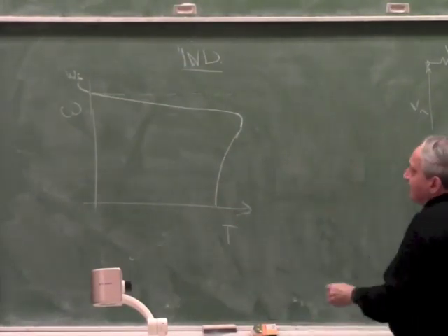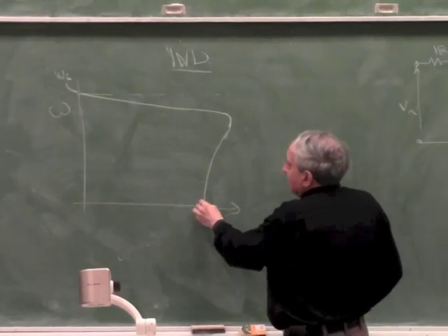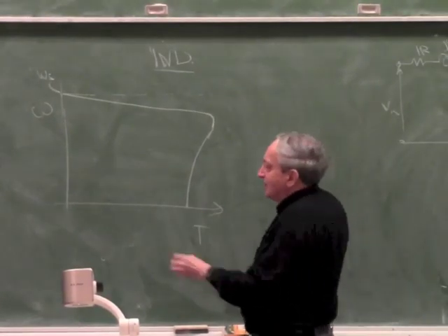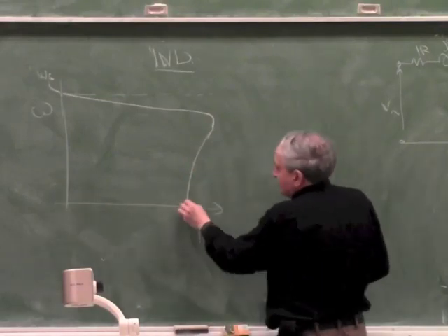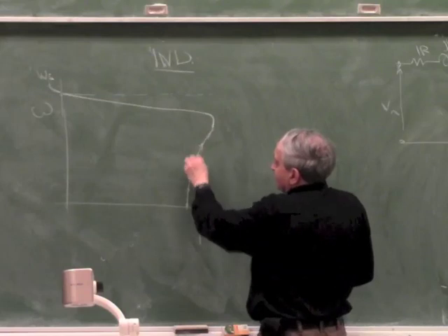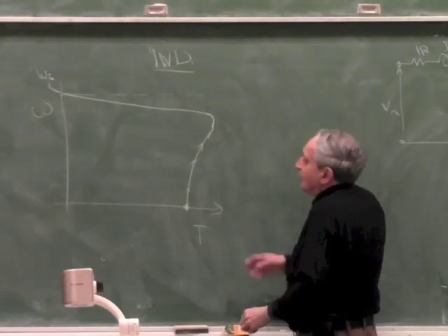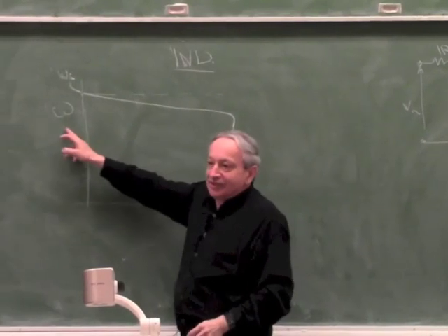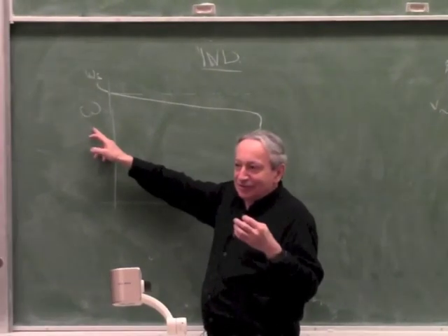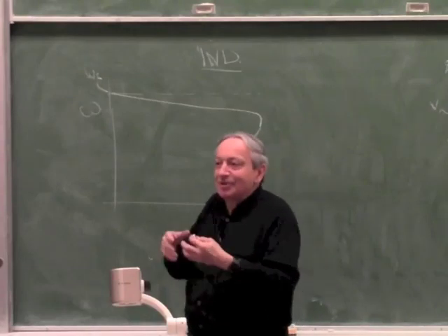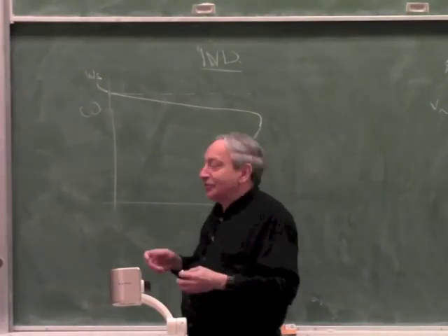It actually has some torque at zero speed. So if you start the motor, it's stalled and you start, it doesn't start from zero torque, it starts from this torque, and as the speed goes up, so this is the starting point, the resting point. As the speed goes up, the torque actually is improving, which is counterintuitive. Because usually you start with the biggest torque, and if the speed goes up, actually you get less torque. Here you get more torque.